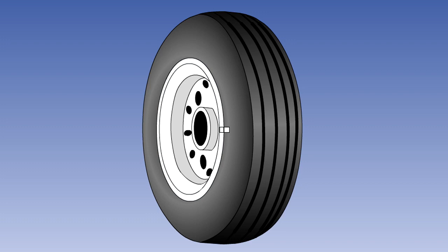When a tyre is first fitted to a wheel, it tends to move slightly around the rim. This phenomenon is called creep, and at this stage it is considered normal. After the tyre settles down, however, this movement should cease. In service, the tyre may tend to continue to creep around the wheel. If this creep is excessive on a tyre fitted with an inner tube, it will tear out the inflation valve and cause the tyre to burst.